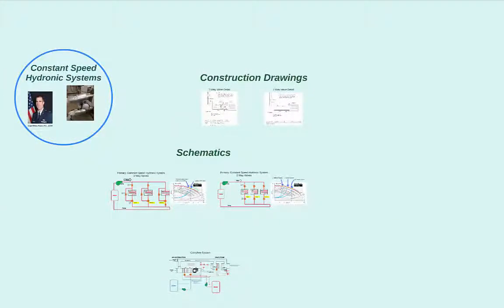Okay, so we have talked about constant speed hydronic systems. We went through a few examples of how these systems are controlled and what occurs in the system as it experiences a variety of operating scenarios. We expanded a bit on this concept of pump curves and system curves, and we use them to better understand how these systems operate. The next lesson will take it a step further. We will provide the pumps with the capability to modulate their speed, and subsequently modulate the amount of flow they are pushing. Such a capability includes the introduction of an additional control loop.